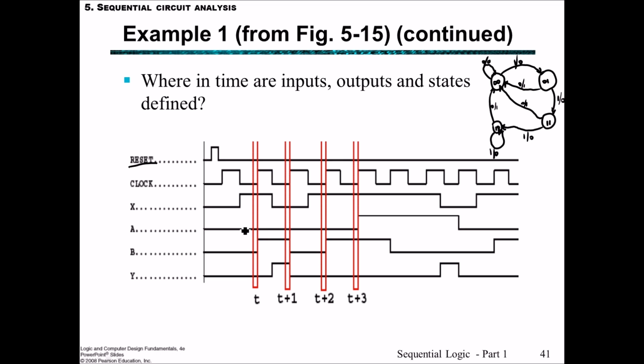And so when the state is 0, 0 from our previous diagram, which I've just put up in this top right hand corner here, when we get an input of 1, then we have an output of 0, but we move on to state 0, 1. So does this happen here? We are at 0, 0 with an output of 0, and we have x equaling 1 and a clock pulse. Then we move on to state 0, 1 with an output of 0. So that's right.